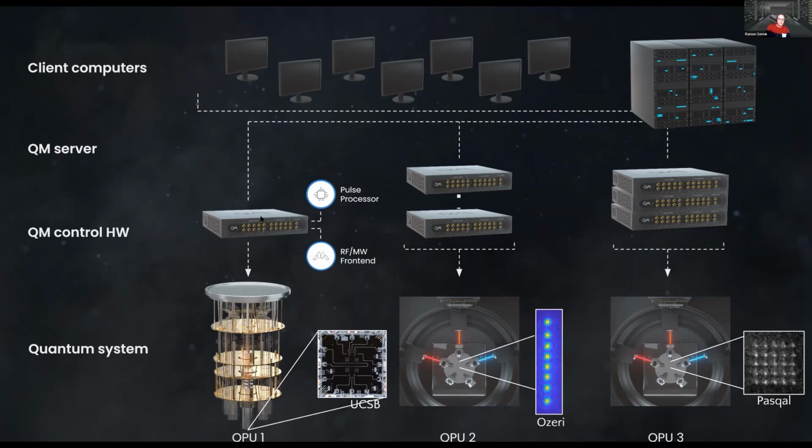We have code for that we will give you freely, of course. And so you can stabilize a laser and do Pound-Drever-Hall with the OPX. You will have a bandwidth of several hundreds of kilohertz. And I will show an example of that in a moment. So yeah, you're connecting from the client and you're executing on many different QPUs that you might have in the lab.